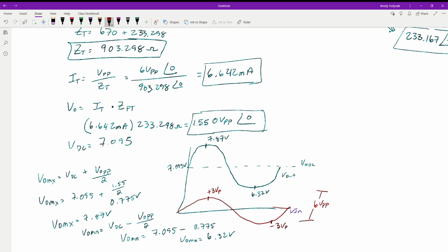So, this is something where we could have a sensor that we want to turn on every so often. Maybe we have, for example, a security system where we have an infrared emitter that we want to basically send pulses, and we're going to be watching for these pulses. And if the distances in between these pulses change, like if somebody walks through the beam, we're going to see a change in the time. That way the system's not constantly on and constantly drawing power. We're going to see the sensor turn on for a little bit, draw some power, then shut off, then turn on, then shut off.